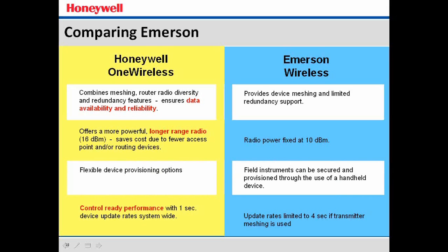We got some pushback from customers, saying that they didn't necessarily want to buy another device that did only that. So we came up with what's called over-the-air provisioning. Over-the-air provisioning is a feature. You go into the wireless device manager, turn it on, go into the field device access points, and turn it on. So you turn it on in two separate places. That allows the system to listen over the air for ISA wireless devices that are trying to join, that don't have a home already.